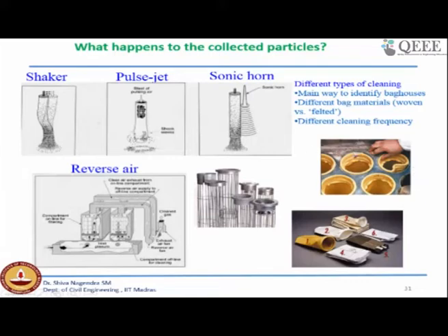Now, another issue you need to consider while designing a bag house is how to collect the particles that are collected in the bag house. Either you can use a shaker, so after a few times the bag house will get a shaking mechanism, or you can use pulse jet or sonic. These are some of the mechanisms you can use to remove the particles collected on the filter inside the bag house.